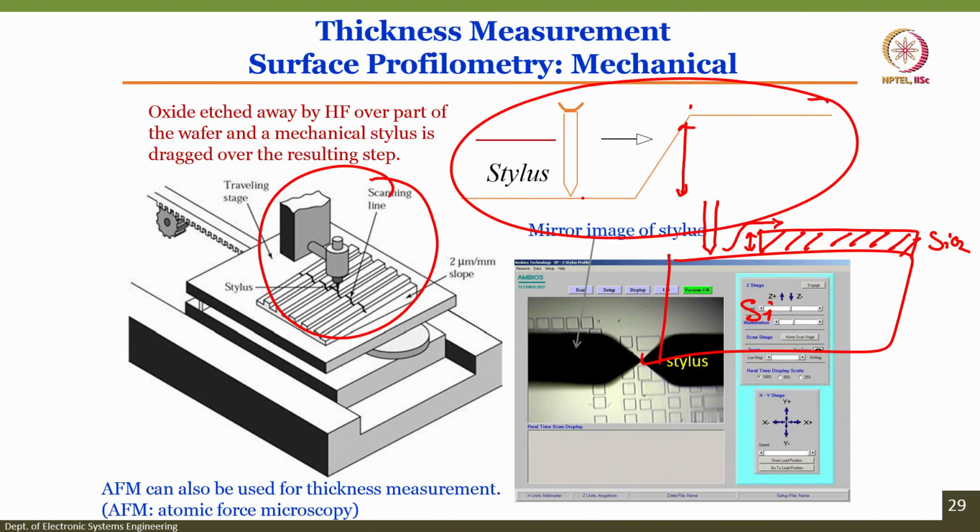If it is single side polished, what is the roughness? If it is double side polished, what is the roughness? If you grow or deposit a material like gold, or zinc oxide, or tin oxide, or indium tin oxide, or indium oxide, what is the roughness of the material on the silicon wafer or on the oxidized silicon wafer? To learn that, we can use the alpha step profilometer or surface profilometry.